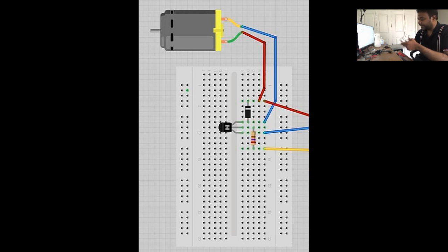That's one problem. The second problem is when the motor stops, because we are setting the voltage to zero, right? When we stop the motor suddenly, there may be a negative voltage spike because of the motor's induction behavior, and that negative voltage spike can also damage your IoT device. So to protect against these problems, we need to use one transistor and one diode. Why do we use a transistor? Because we know from basic electronics that a transistor acts as a switch, right?